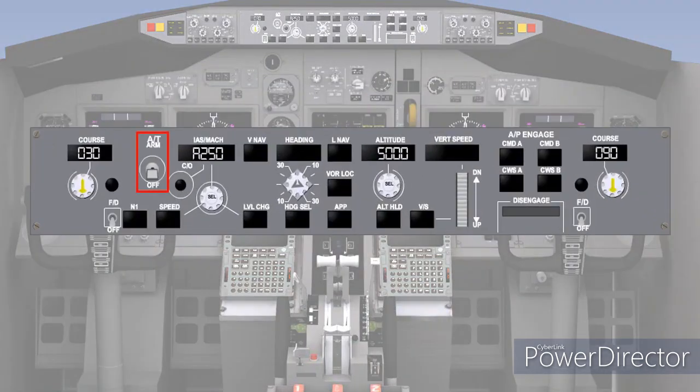In this lesson, you will learn about the pitch or secondary axis flight path modes used by the autopilot. In most modern airliners, there will be an auto-throttle system, which will operate in conjunction with the pitch channel of the autopilot to control climb, cruise, and descent functions. One of the following pitch functions can be engaged simultaneously with a roll mode: altitude hold, vertical speed hold, and altitude acquire, which engages automatically on the completion of a climb or descent.